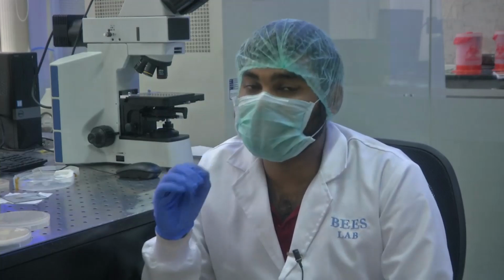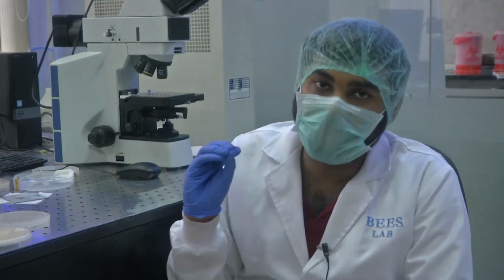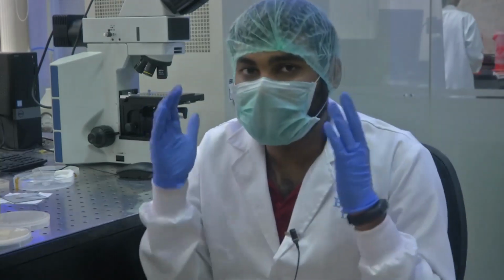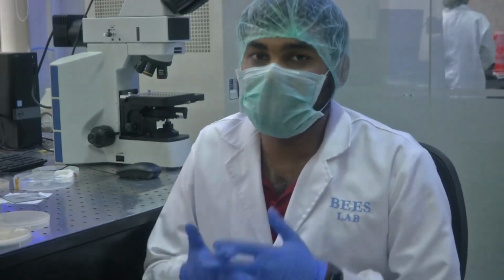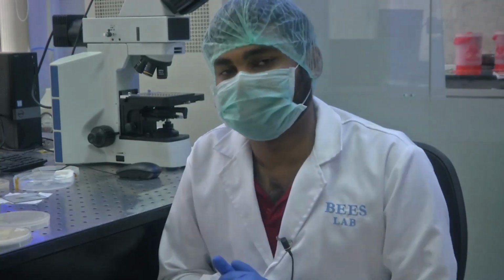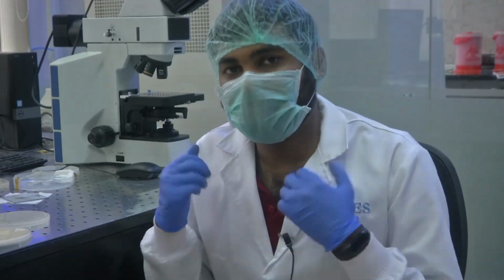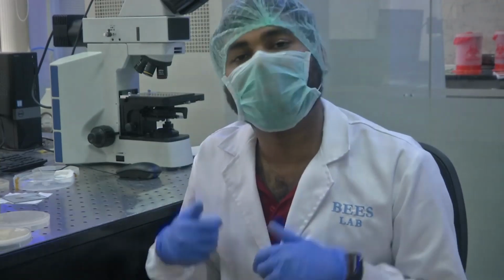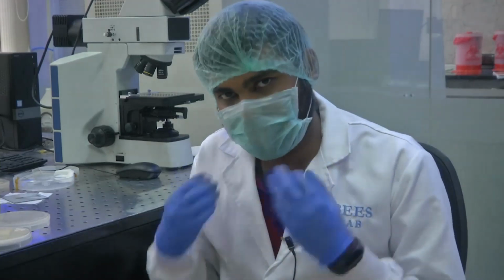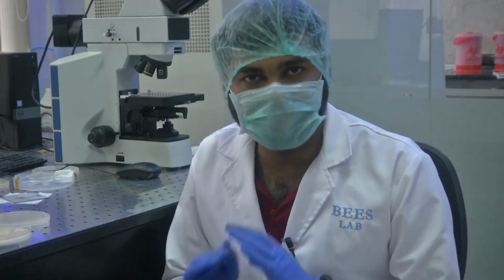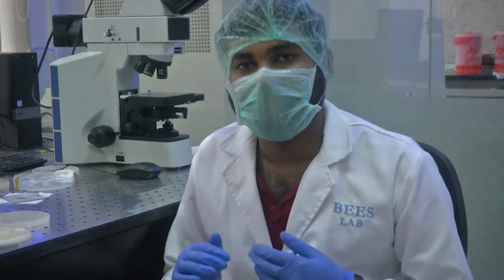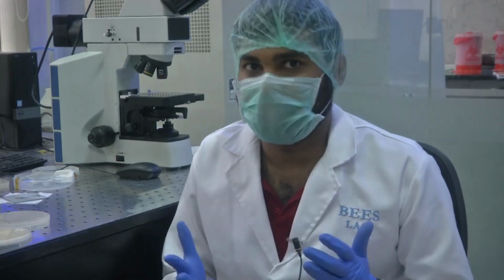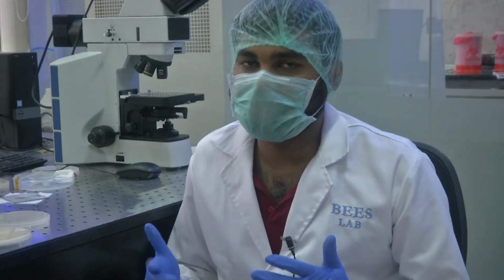But if you are looking at an electrode, a thicker layer of material makes sense because its inherent resistance will be low. The electrode should be able to sense the impedance or the resistivity or the resistance of the substance that is on top of it, correct. When you are measuring such a property, the inherent resistance of the electrode itself should be as low as possible. If that is the case, then it makes sense to have a higher area. So rho L by A, if you make A higher, then resistance will be less.